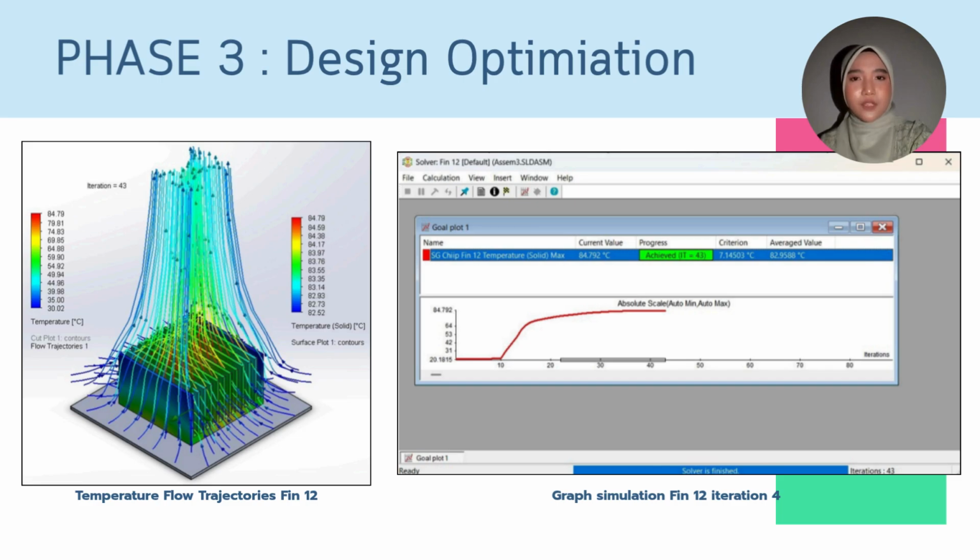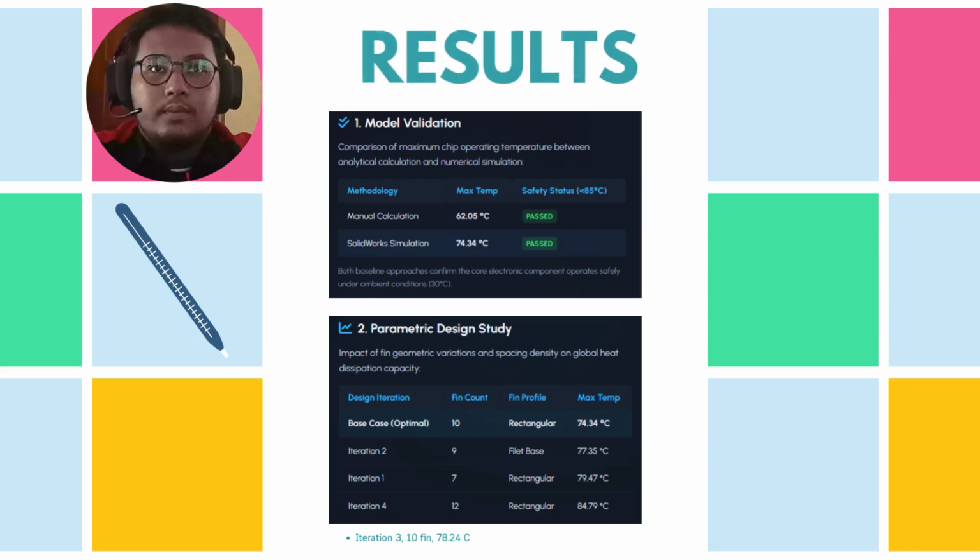This design failed to improve cooling because the closely packed fins choked the natural convection. The restricted air channels trap warm air between the fins instead of allowing it to rise freely, demonstrating that for passive cooling, balancing fin spacing is more important than merely maximizing surface area.